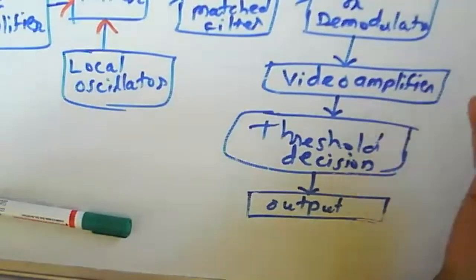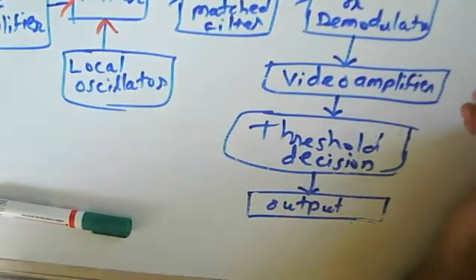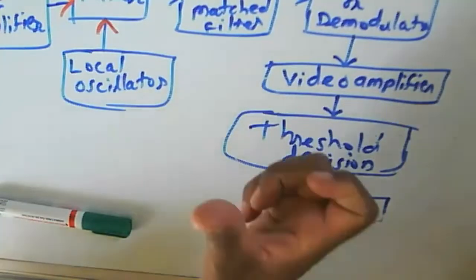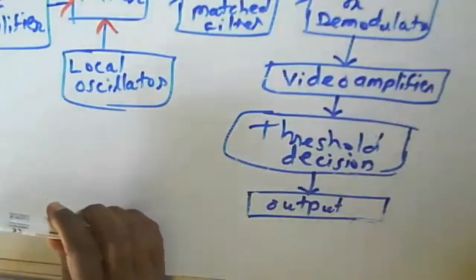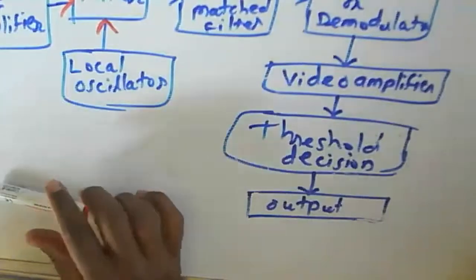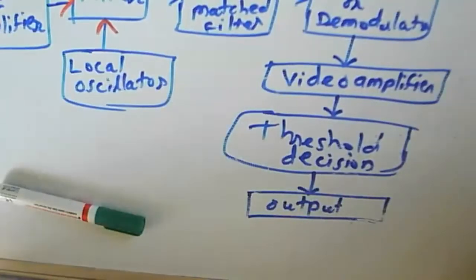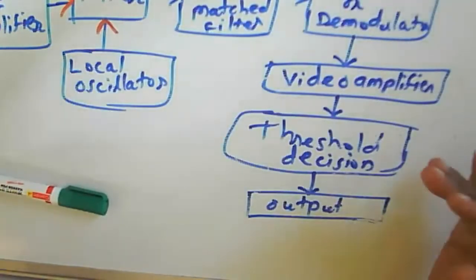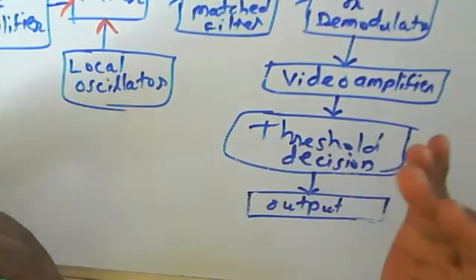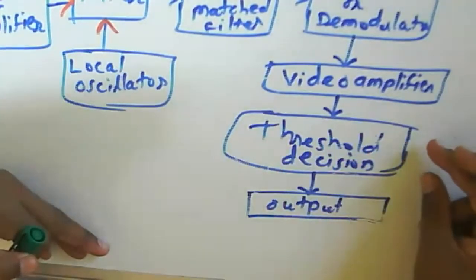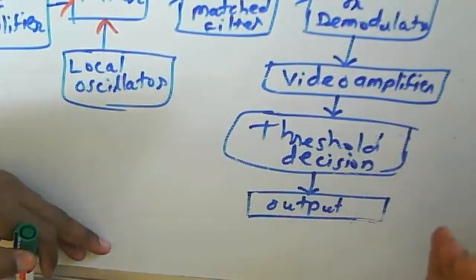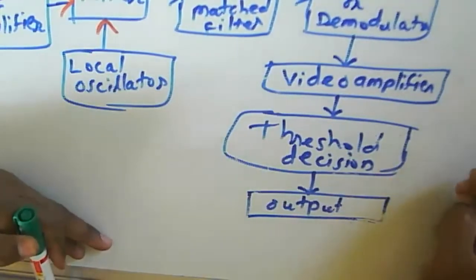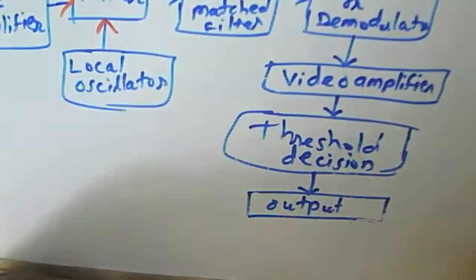So why does this happen? In a military application, sometimes a false signal is sent for a given particular range, or a jamming signal is sent. In that case, that false alarm is detected by the device. So we need to know what the false alarm rate of a device is. It depends upon the threshold we have selected and the noise level we have selected for detecting the given particular object.